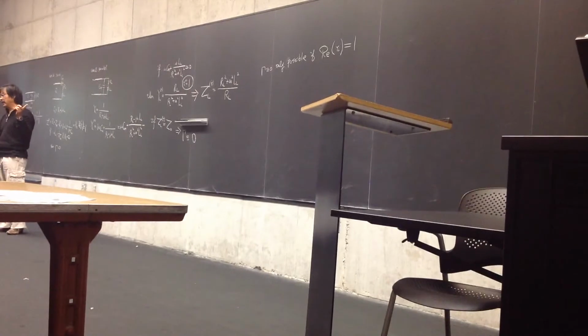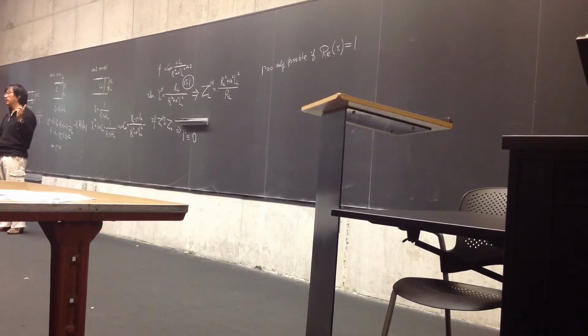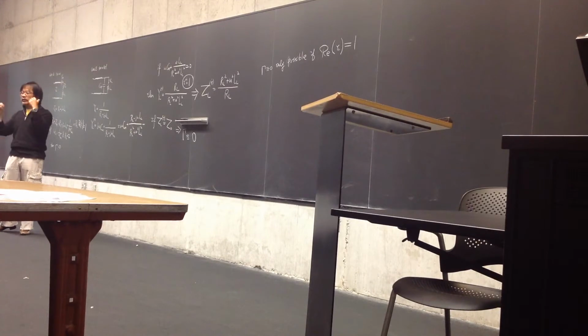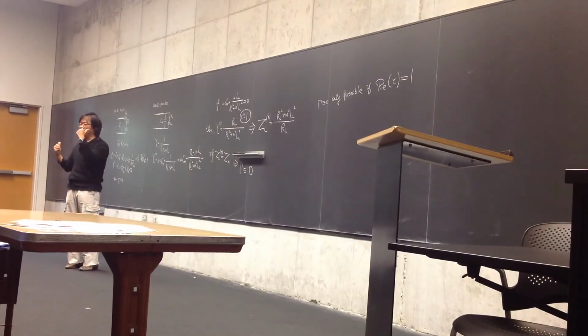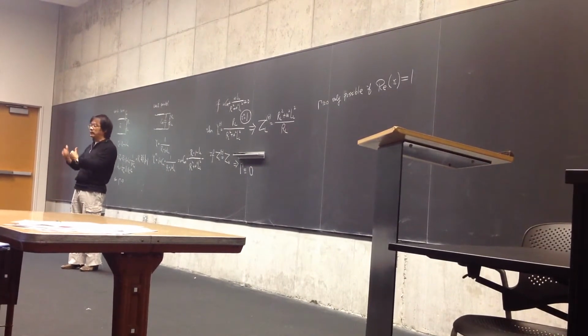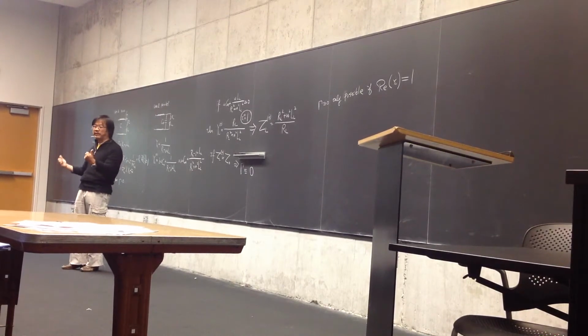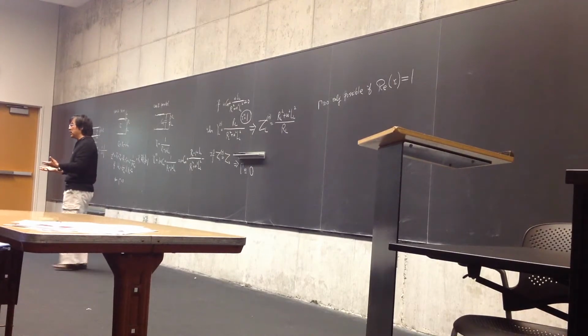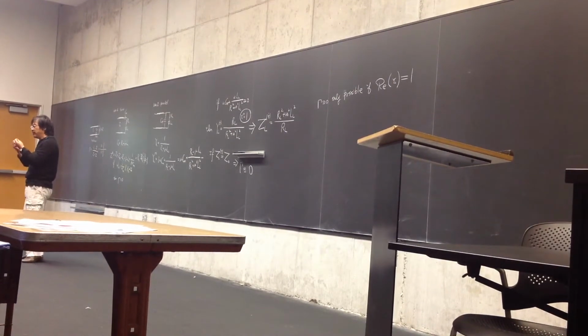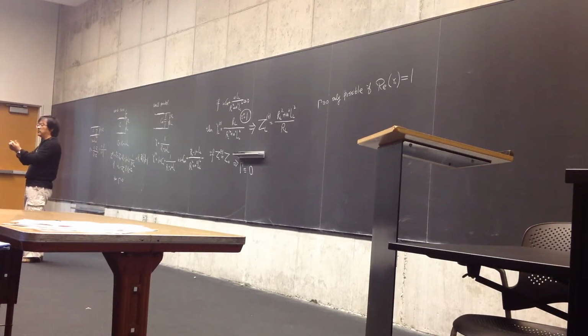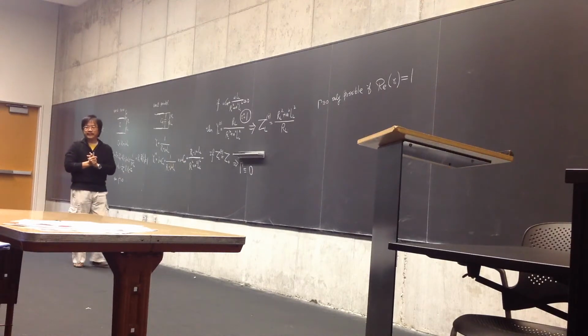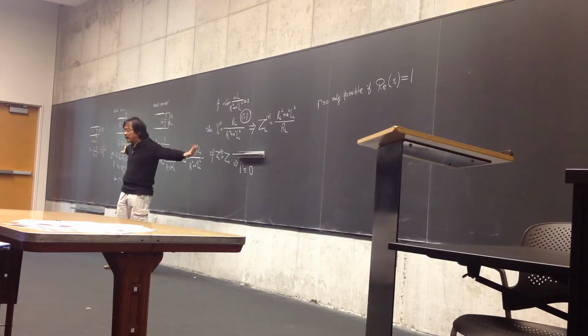When I think about the admittance, I normalize with respect to 1 over Z0. Okay, in other words, I normalize to Y0. So you see the point here. When you are talking about the admittance, you normalize to the admittance of your transmission line. When you are talking about impedance, you normalize with respect to the impedance of a transmission line. When you talk about normalized, it's a dimensionless number. So, follow me there. So, there are these two ways.